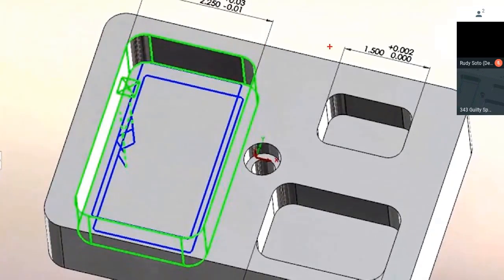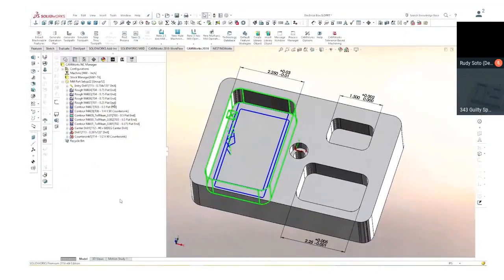So the machinist is going to have to go in there and manually modify the toolpaths for these pockets that have the tighter tolerance. Well, now they don't have to, because the software, CAMWorks, can actually read this PMI and use the PMI to dictate what type of toolpath is going to be utilized in each of those pockets. So these are the time-saving benefits of getting into PMI and utilizing it in downstream applications. And hopefully this will help you ask the right questions when it comes to buying the tools for inspection or buying the tools for machining software.